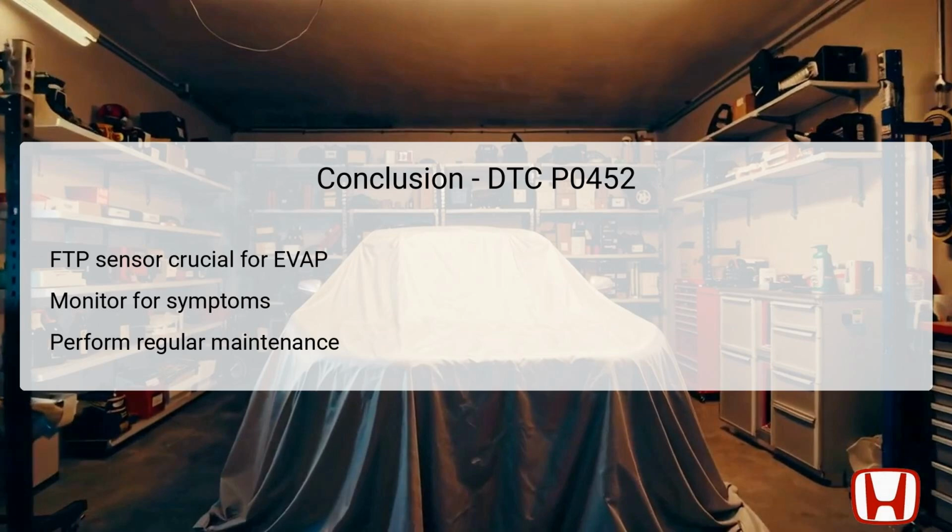By following a methodical troubleshooting process, involving checking for open or short circuits and verifying repairs, technicians can effectively resolve the issues linked to this error code. Additionally, implementing preventive measures will go a long way in maintaining the integrity of the fuel system and the functionality of the FTP sensor, helping avoid similar problems in the future.